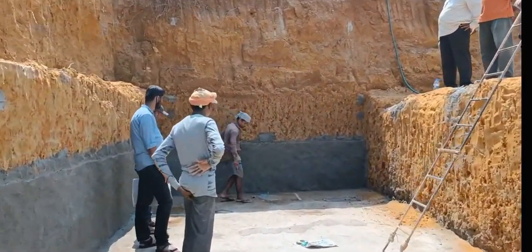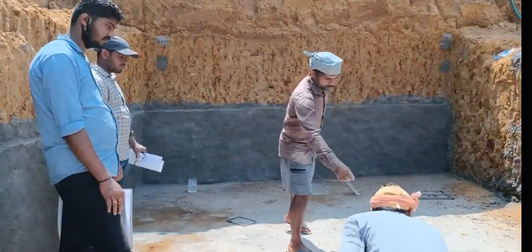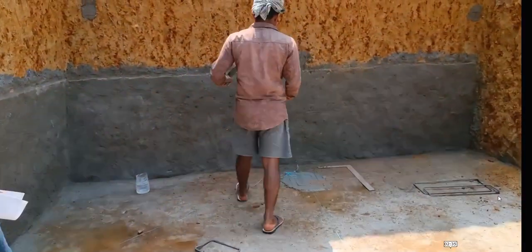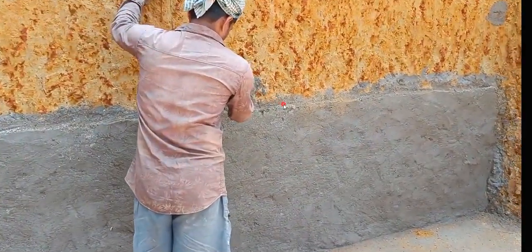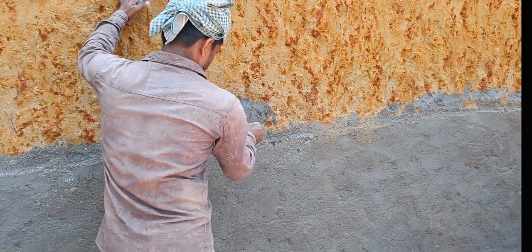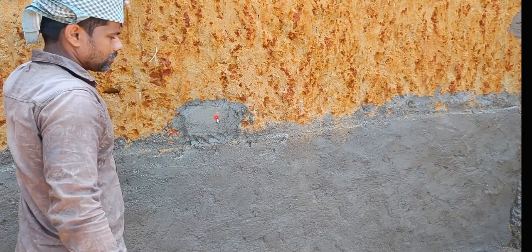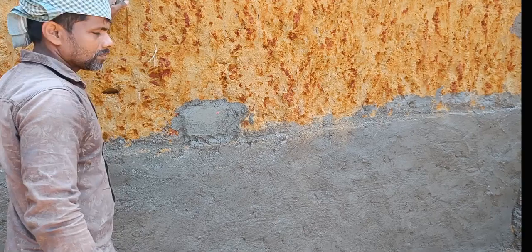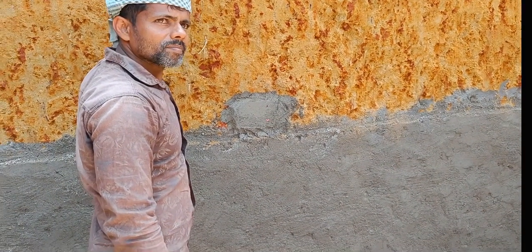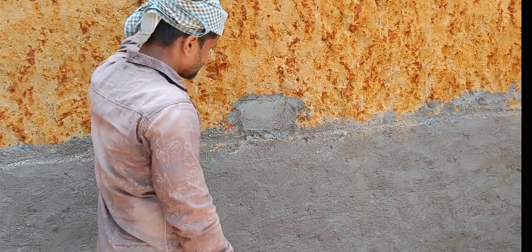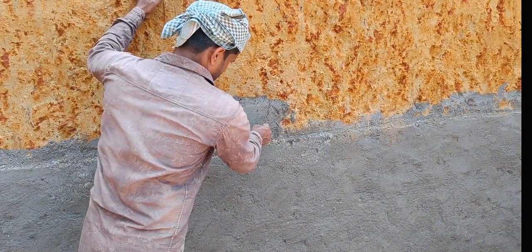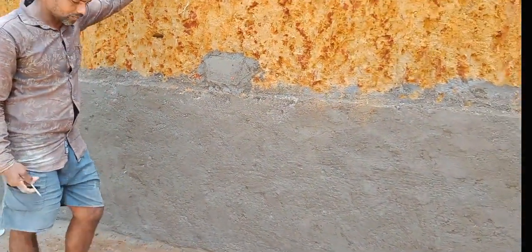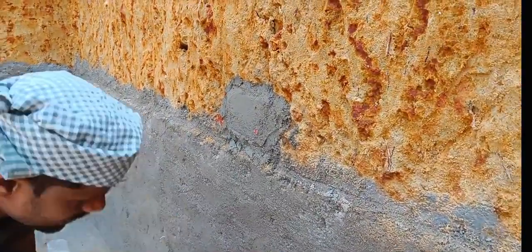Observe there. You'll find a laser. Yeah, you can see the laser, how it is pointed. Now you see this is a red color laser. This is that exact point which I wanted, that is a grid line. Once you project that, he has to adjust it. Okay, this is that exact point where we wanted, and once it is done, we'll insert a nail there, or we'll give a small line to that. Okay, done. You're able to see that laser, it's blinking.